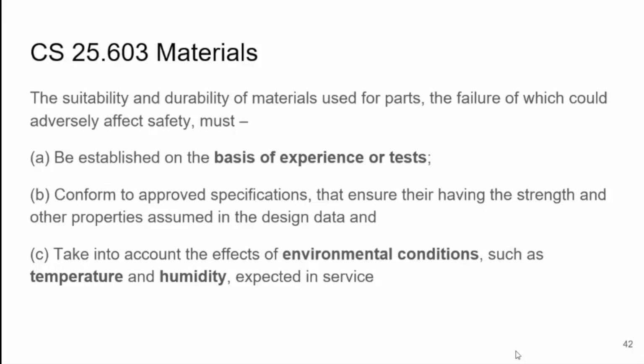So if you do composite, then there is no experience. You cannot say, I'm using epoxy and you are also using epoxy resin system, so it is the same. It may not be the same, because it depends on your manufacturing process and on how you design your laminate. So basically, most of the time you have to come out with the material properties by extensive testing. And during the test, you have to take account of environmental temperature and humidity, whatever you think will affect the aircraft in service.